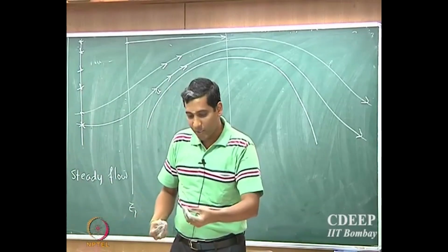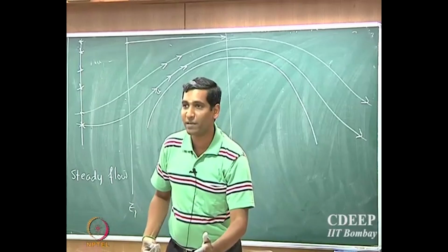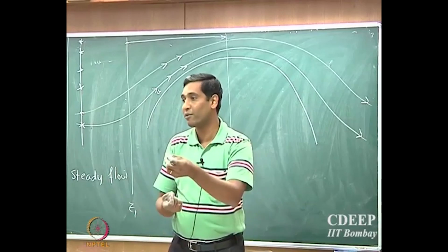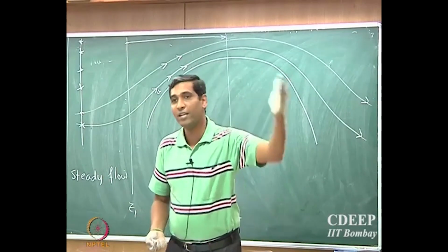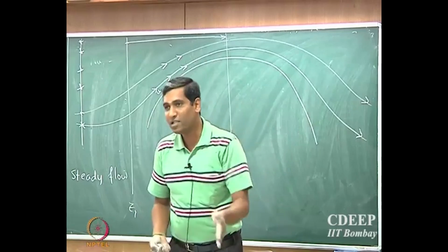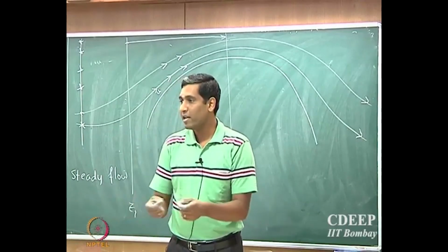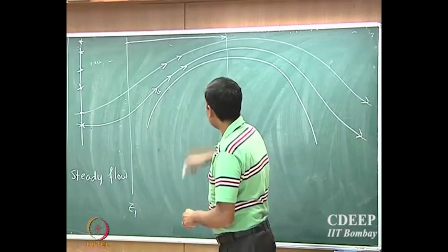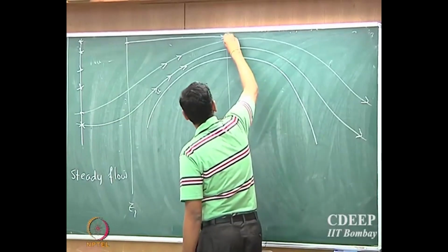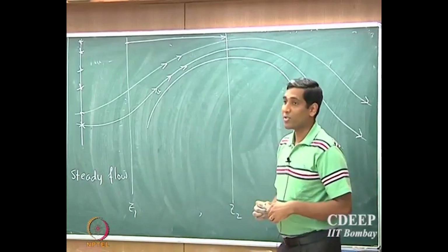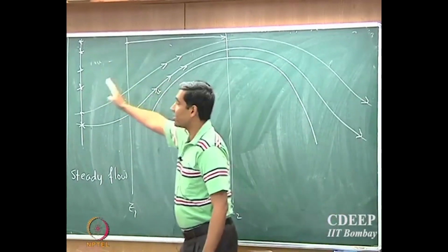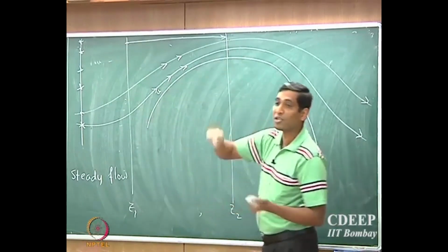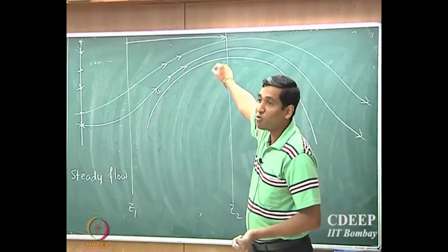In a flat plate, what happens is that the momentum which is present before the flat plate is experienced is distributed because the fluid particles are now moving in both x and y directions. If you have fluid moving only in the x direction before the plate is experienced, but in the boundary layer, because of the presence of the flat plate, it's moving in both directions, the effective mass flow is the same. Unlike in the cylinder, where if you want the same mass flow rate, or the same fluid particles which started at some location to cross the same point, then the fluid particles traveling a larger distance have to accelerate in order to catch up.